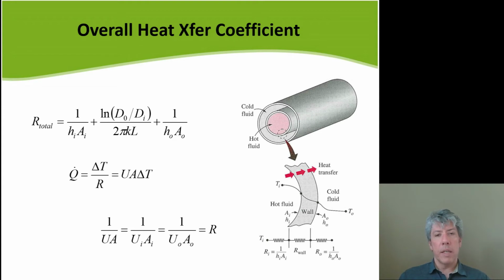And so if you look at the equation at the bottom, usually you want the thickness of that pipe wall that separates the hot and the cold fluid to be as thin as possible. The reason is because you want its resistance to be as small as possible. And so the inner area, A sub I, of that little tube in the middle, where the hot fluid is in contact, and the outside area of that same tube, where the cold fluid is in contact, A sub O, they're often very close to one another. There's often not much difference in the amount of area inside and out.